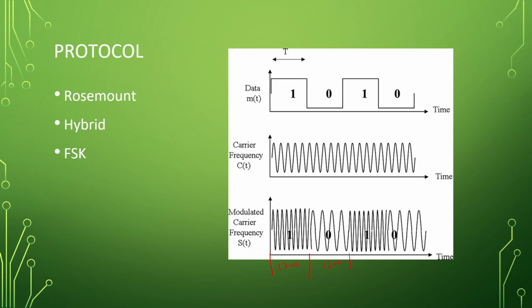All right. So, if I have my little chart here, right, and here's 20 milliamps, here's 0, and I'm sending this signal right here, all they're doing is they're now imposing this frequency on top of that. So the average current flow is still the exact same. And they're, again, relying on the fact that devices don't see these high frequencies. They have to average them to be able to then do this.